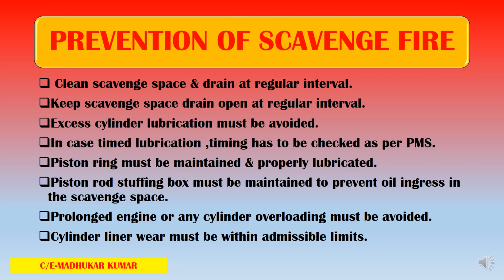Piston rod stuffing box must be maintained to prevent oil ingress in the scavenge space. Yes, very good. Prolonged engine or any cylinder overloading must be avoided. Overloading is not good for the health of the engine. Whatever is required for a certain time duration, if there is an emergency, that is another issue. Otherwise, it should be avoided. Cylinder liner wear must be within admissible limits. Cylinder liner wear is measured on a timely basis as per routine, and this wear has to be within the limits prescribed for that particular engine. If we do all these things, we will be able to prevent the scavenge fire successfully.